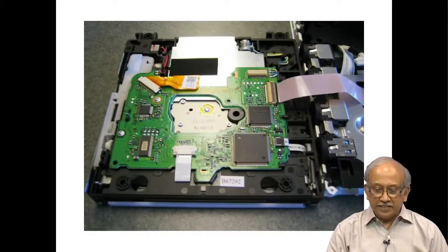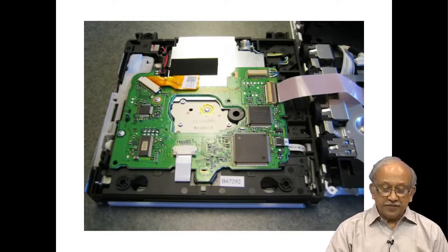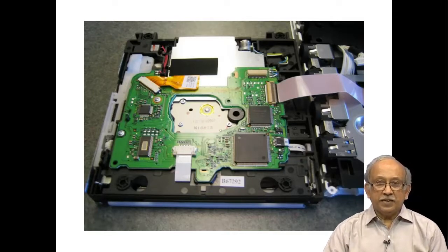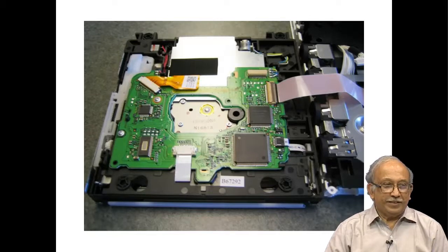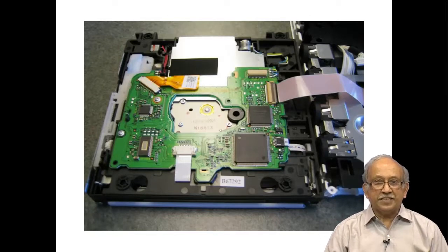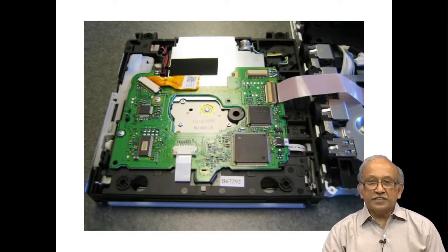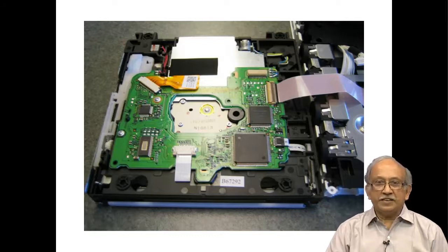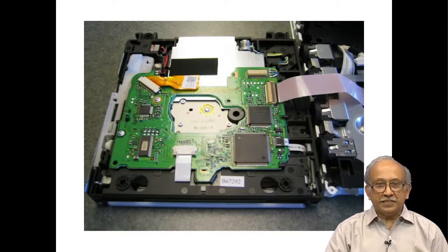And now further, if you go inside, you see here we have a printed wiring board. This printed wiring board, contrary to normal lab exercises, is rarely a rectangular shape. I have no criticism about it. As a lab exercise, it is worth trying to lay out a PCB taking the four corners of the screen, because you can learn how to lay out a PCB, how to make a schematic capture, how to make a rat nest, how to do routing, and how to space all the components properly.